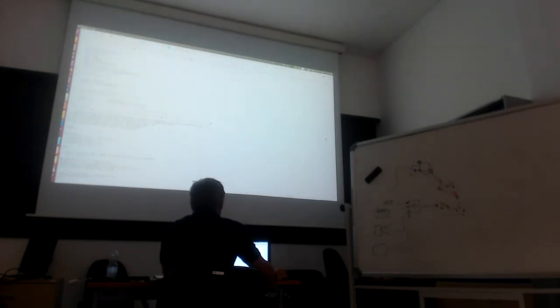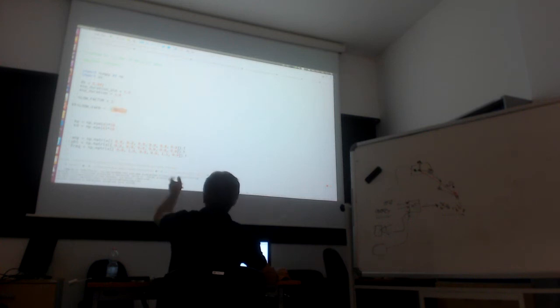So in essence, you can see this is the code. There is one config file called ex1 conf, where you can set the sampling time of the controller and the duration of the sine. You can slow the motion, if it is too fast, with the slow factor, and define the frame name that is called ee link.